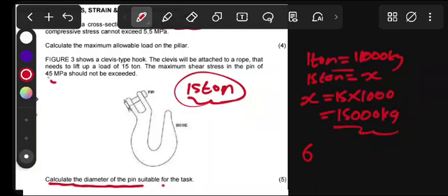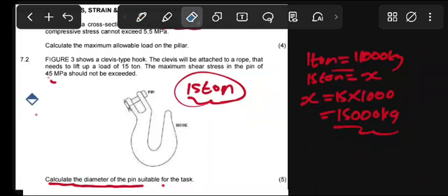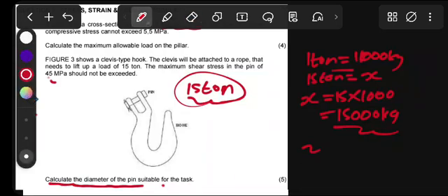You know that we have the board. We have been given the shear stress. The shear stress is equal to what? Force divided by area. But now remember, because it's a pin, it will be sheared there twice. You'll multiply this by 2, guys.